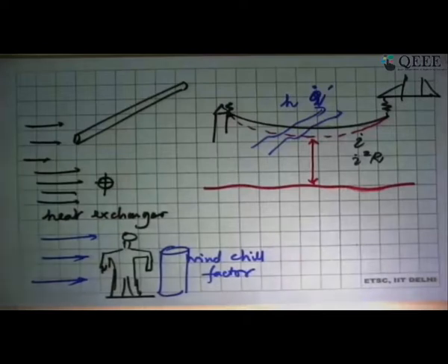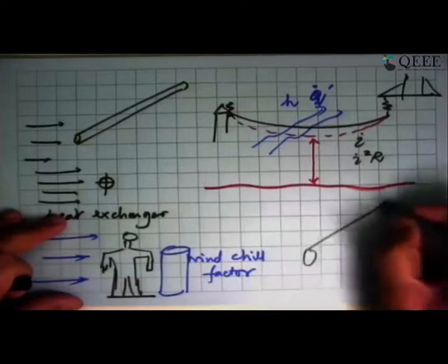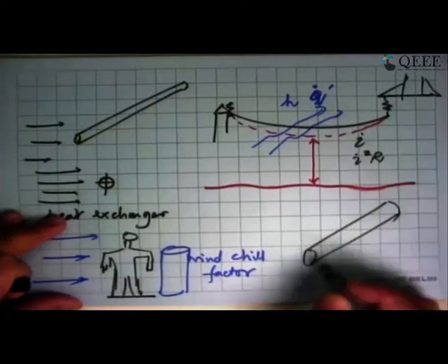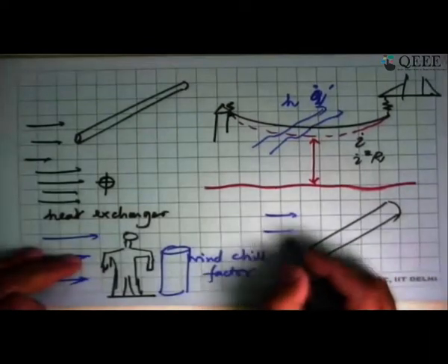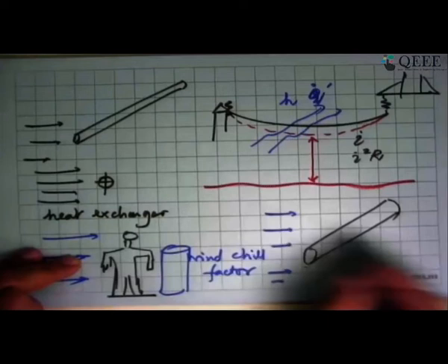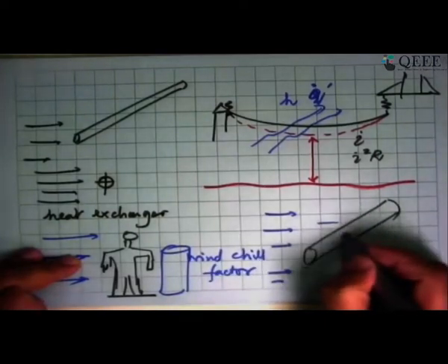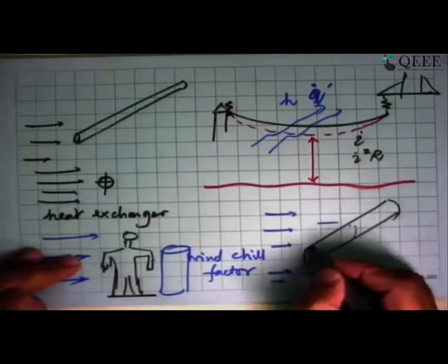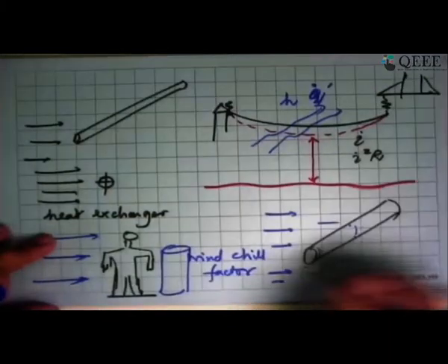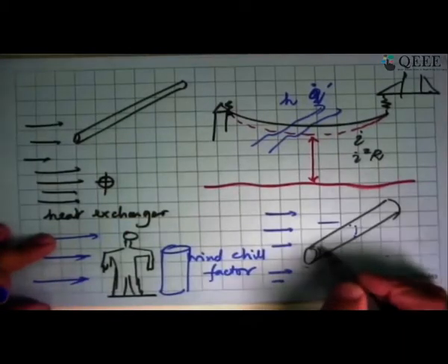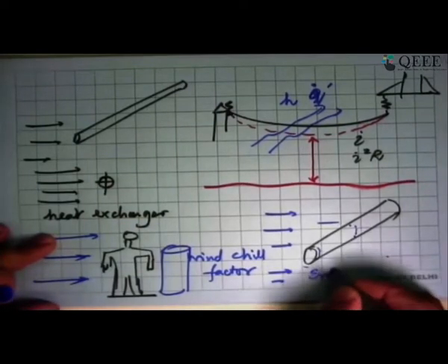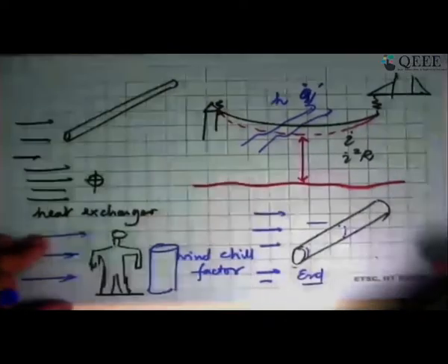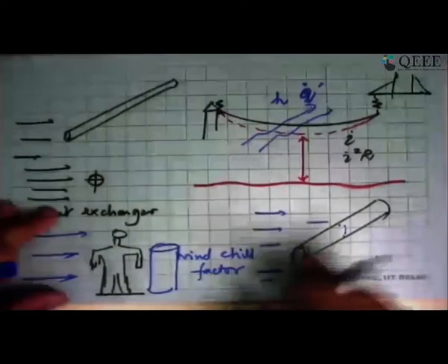And see what happens. So that's the next assumption we make in analyzing flow over a cylinder, that in all these cases we have taken that the cylinder is long, the flow has no other surfaces, which is why it is external flow, and the ends will not have the flow that is happening in the middle part of the cylinder. It will be different from what happens at the end, because if you look from the top view, air can even go like that. In the center, it is not going to happen. So the end portion will be slightly different from what happens in the center. In a real problem, you'll have to factor this in also, but that makes life much more complex.